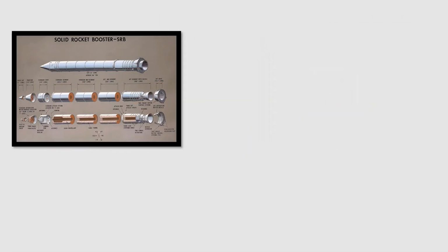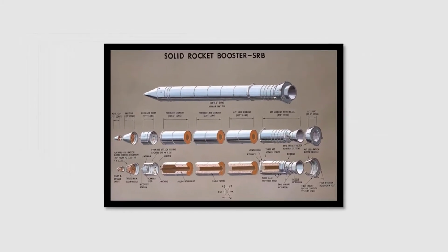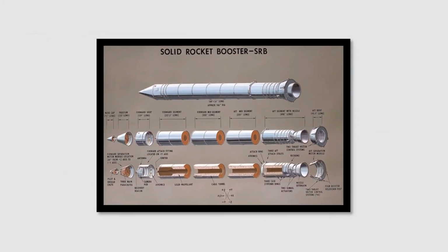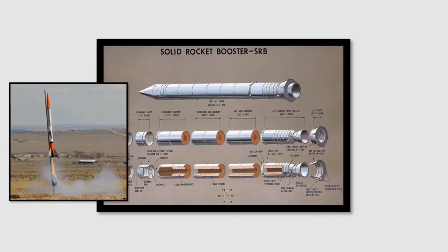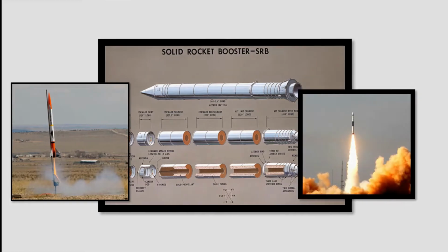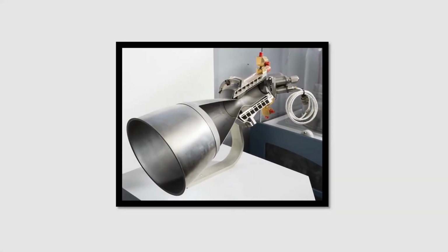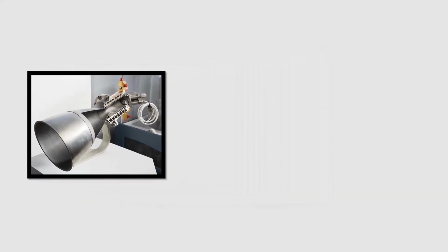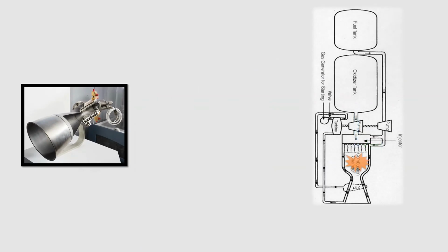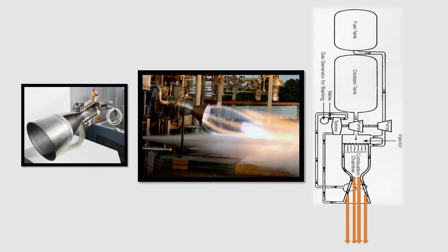As indicated by its name, solid engines are tubes of solid fuel that burn steadily and uncontrollably until there's no fuel left. These kinds of motors are found on almost all model rockets and some full-scale rockets. Perhaps the more widely used motor is the liquid fuel motor. This is where liquid fuel and oxidizer is mixed and ignited so that the expanded gases from the burning fuel shoot out the back of the nozzle at high speeds. This engine has the benefit of having control over the fuel and how much of it is burned, making it a very popular choice for modern rockets.